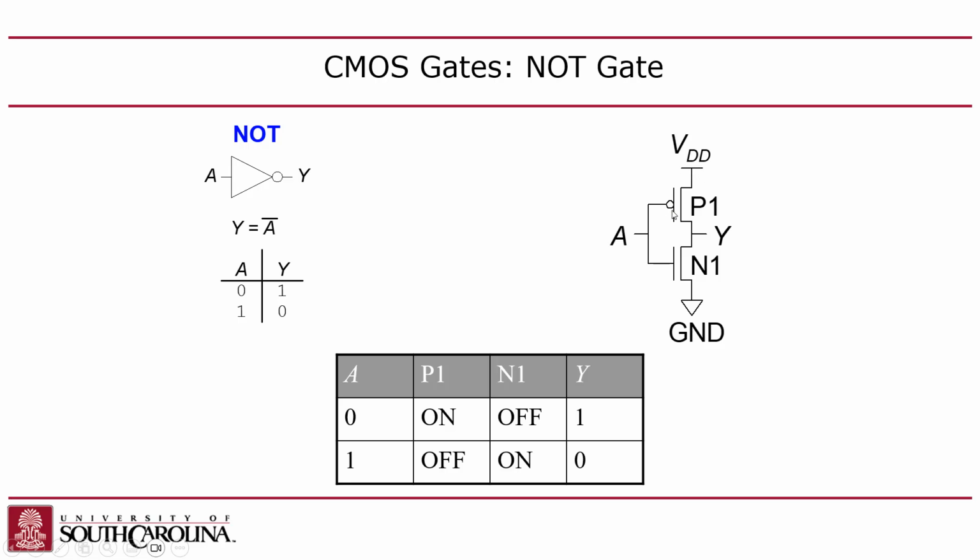So when you put a 0 on this PMOS, you're actually putting a -1 on there, right? But logically, it's a 0. So that's the reason why you need to have PMOSs as your pull up, because you have to reference the gate to VDD in order to get a negative threshold voltage on there. So digitally, again, it's 0 turns on the PMOS. In analog, it's actually some voltage less than the negative threshold voltage, negative 700 millivolts, right?